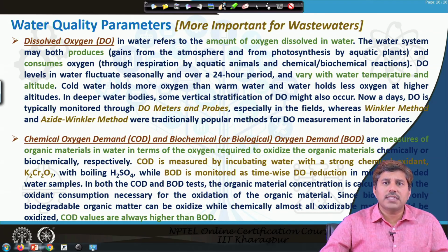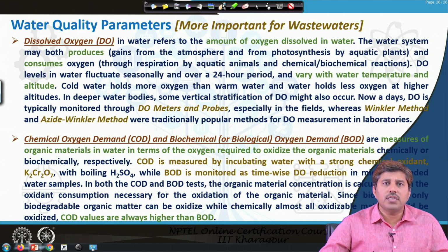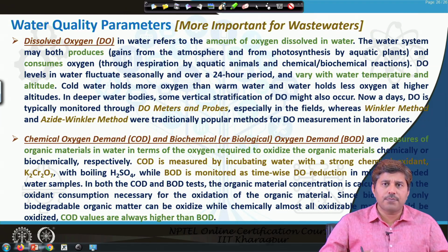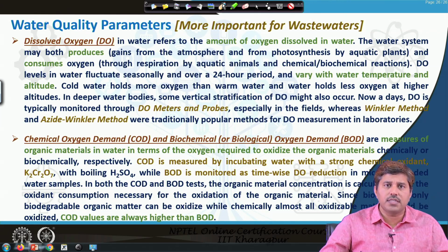Both actually are indirect measurements of organic material, but COD measures it chemically with a strong oxidant, which can oxidize almost all oxidizable elements in the water, whereas BOD measures the approximate amount of organic matter which can be oxidized biologically. So, biologically only biodegradable organic matter can be oxidized. So, BOD is an assessment of the biodegradable component of organic matter, whereas COD is an assessment of almost all the organic matter present in the water,